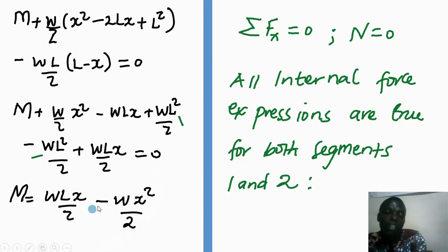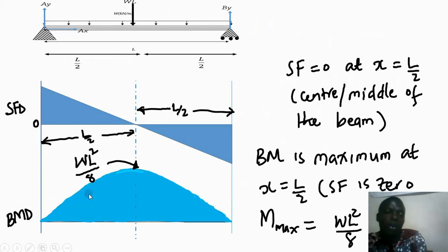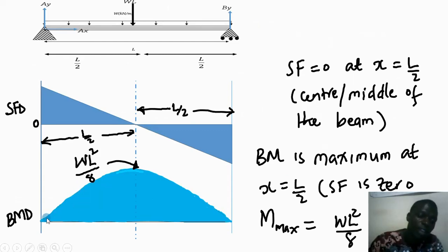So you need to understand the mathematics behind a parabola if you are to draw this diagram also. Therefore, the points will be equidistant from the axis, and I will have those points plotted and join them, and this will be the bending moment diagram.